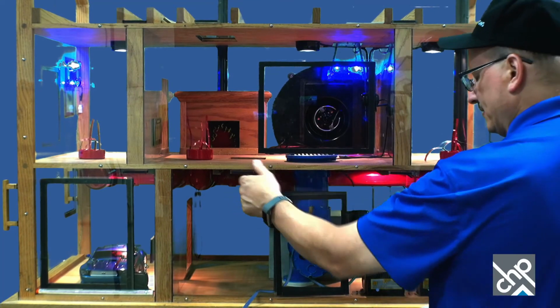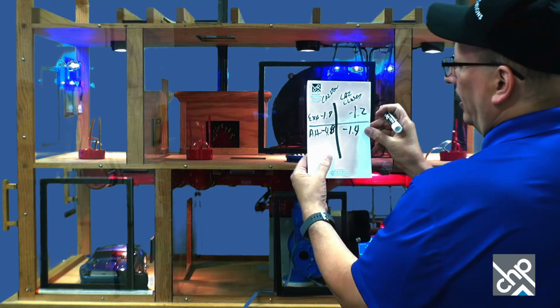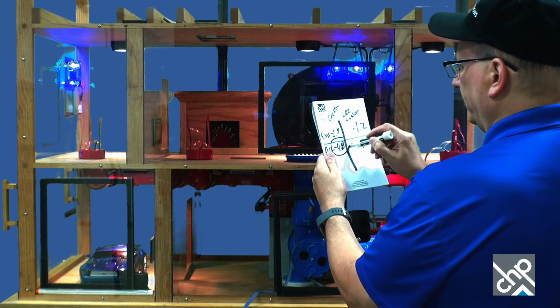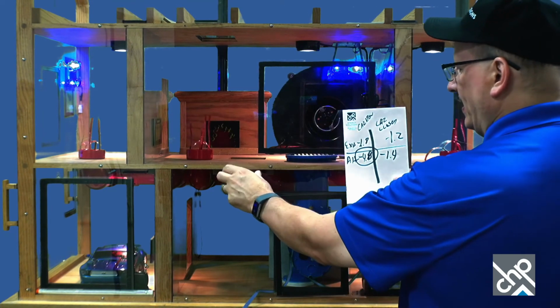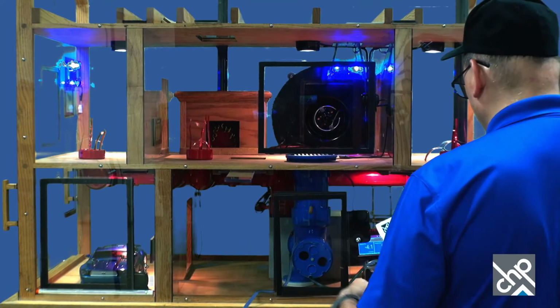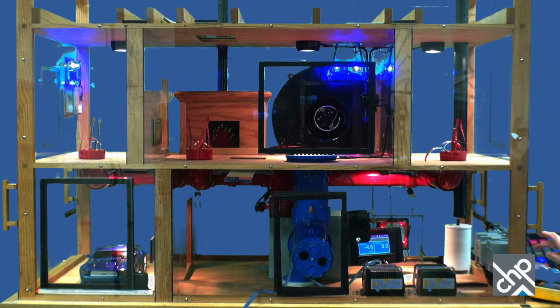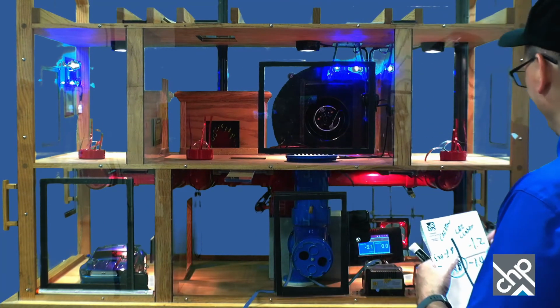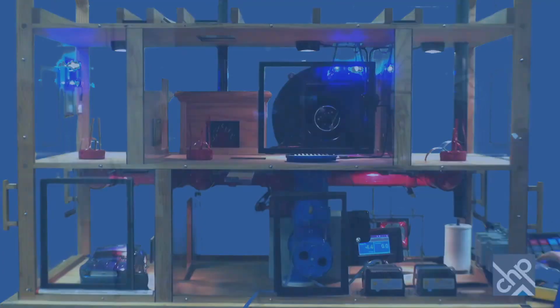So worst case, if I look at these numbers here, I had 1.8 negative, 1.2 negative, 4.8 negative, and 1.4. The worst case was negative 4.8, and that was with the CAZ door open. So now if I go back down to the basement here, you would see that we're somewhere similar to that, at that same negative pressure. So that would be our worst case. We would fire up our water heater, so test spillage. So you guys want to do that? So I'm going to close this back, put this back, leave it open. We're in worst case. Go back down to the basement.